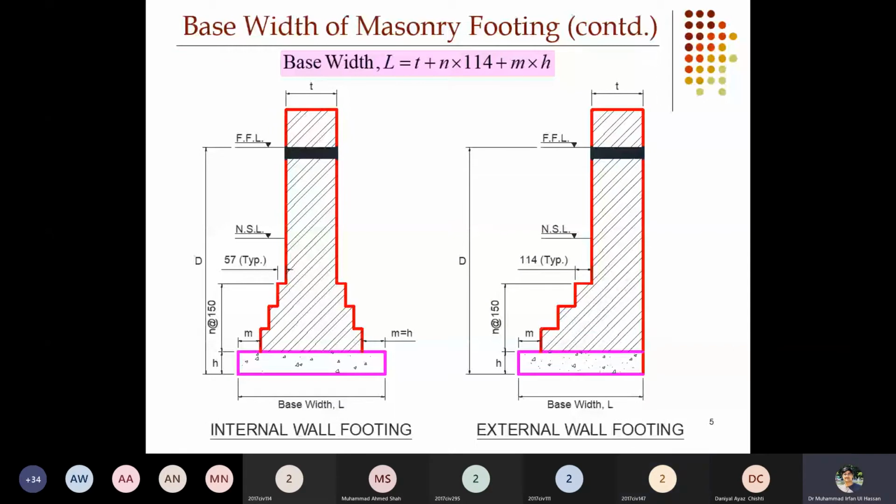That is just like the same footing. I mean, the footing is the same because it's a wall footing. So the section of the corner footing is the same. Just the load, you have to increase the load by 70% for providing the corner foundations. But for the section, if you can go on both sides, then it will be a left side section that is visible on screen. But if you can go on only one side of the footing, then it is a right hand side section.